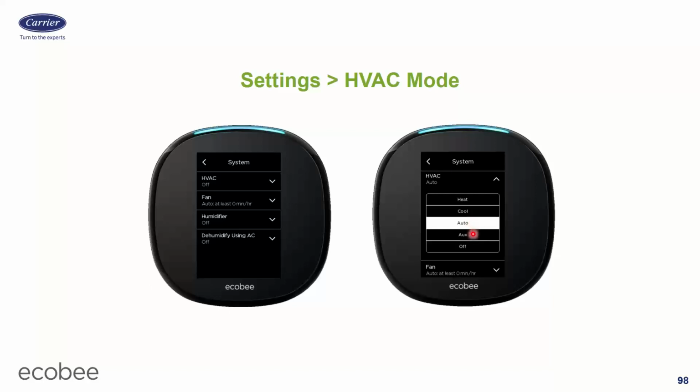The only time you'd put it in aux is if your compressor died and it's not running, and then I want to force it to run the furnace or electric heat. Then I'll force it to go into aux. Other than that, you leave it in auto and let it do its thing.